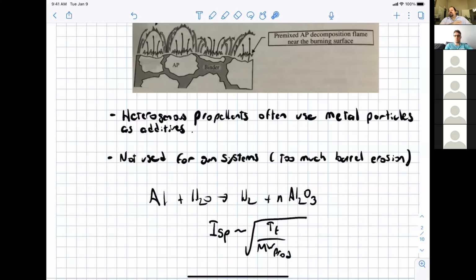That acoustic wave will bounce off the walls of the rocket combustor and then further increase the burning rate of the propellant. And this process repeats itself over the span of 10-20 seconds, and all of a sudden your rocket is in 1,000 pieces. Those are called combustion instabilities in rockets, and those are very, very non-desirable.